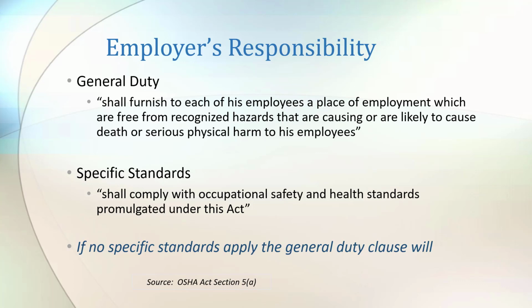And we'll talk about hazards a little bit later. But a recognized hazard is a hazard that's recognized by a professional, an employee, the employer, or industry standards. And I'll give you an example. Everybody knows that working on top of a building next to an edge on a construction site, so you're building a building, most people know that those workers need to have fall protection on.